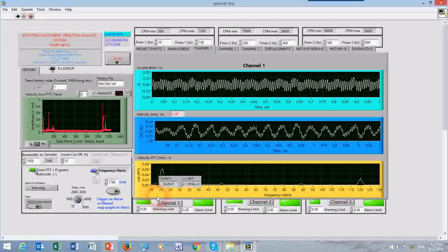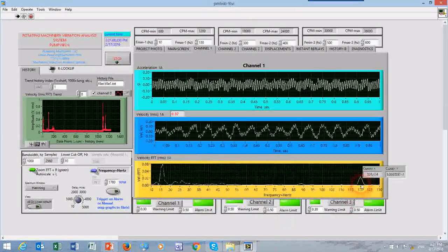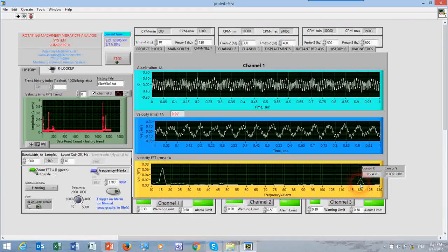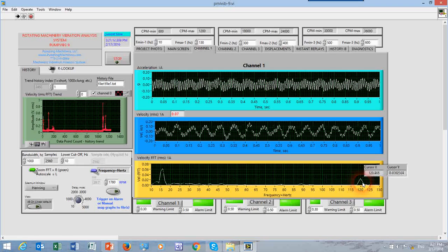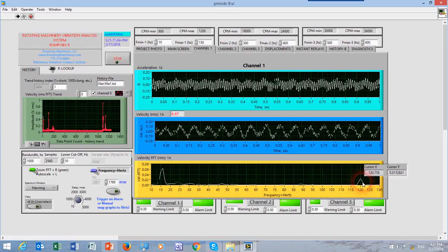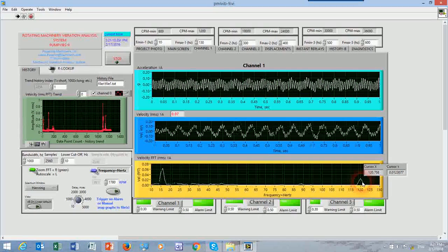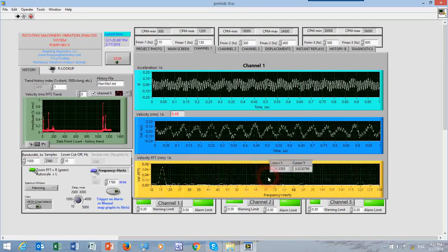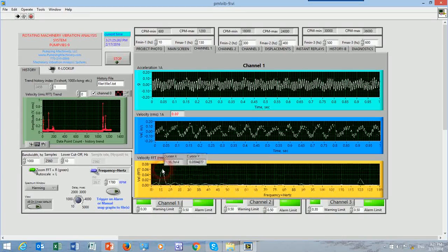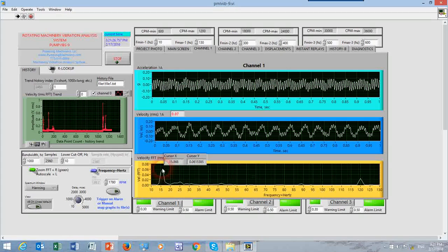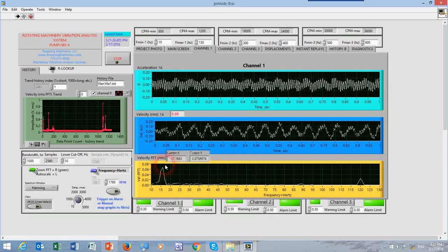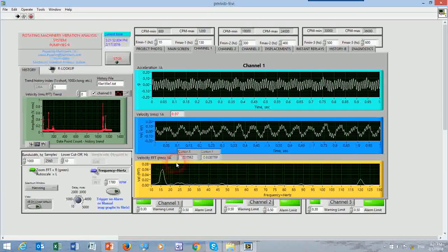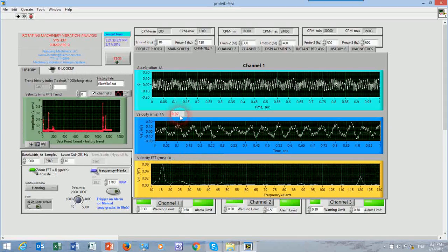And now we see two peaks at 16 and 120 hertz. 120 hertz is probably electrical noise, 60 times 2. And the 16 times 2 harmonic, we really don't see. So the bulk of vibrations is coming from the 1x fundamental frequency, which might be indicating unbalance, although it's not very significant unbalance because velocity is relatively small, 0.07.